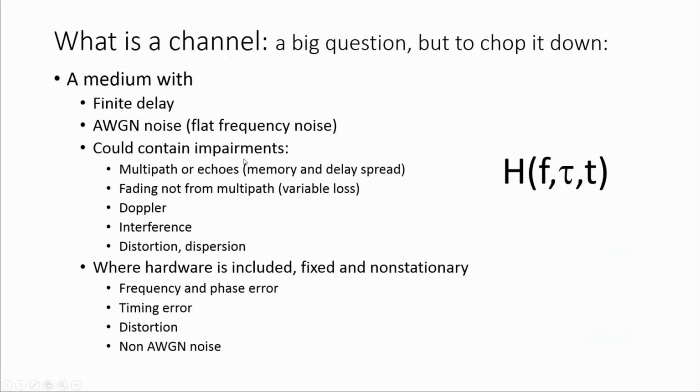This is the most important thing for the channel, multipath. We don't deal too much with multipath at HF, but at higher frequencies, you can start seeing where this is a problem. So in narrowband channels and long wavelengths, multipath doesn't have too much of an issue. But as you go higher in frequency and you have more bandwidth, multipath becomes a problem because it functions like a filter, and it not only causes fading, but it also causes frequency-dependent fading, which is terrible. It definitely has to be repaired.